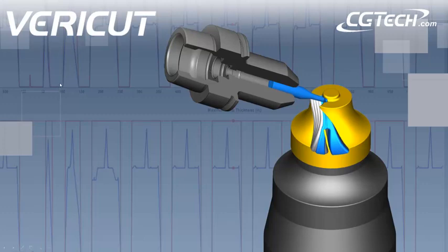By optimizing using VERICUT Force, you'll be able to optimize NC programs that you're programming today in your newer CAM systems with the more advanced cutter paths, and also your existing cutter paths that you have laying around the shop. The same software optimizes them both to give you ideal constant chip thickness as much as possible while simultaneously reducing any excessive forces or spindle power or deflection.